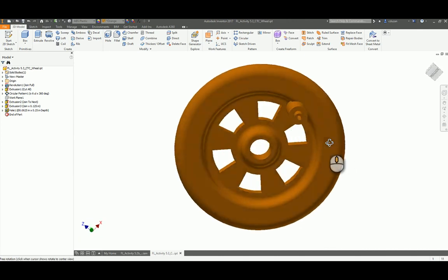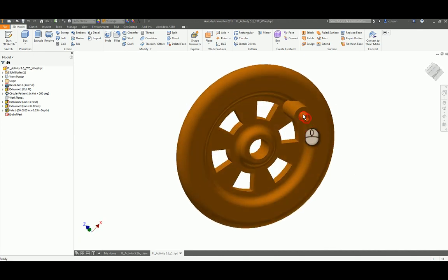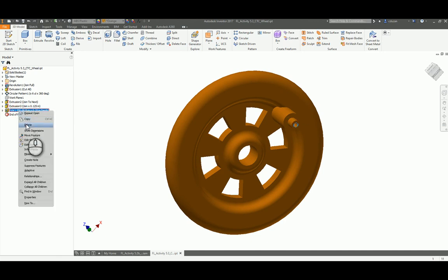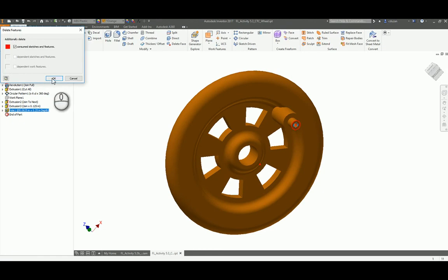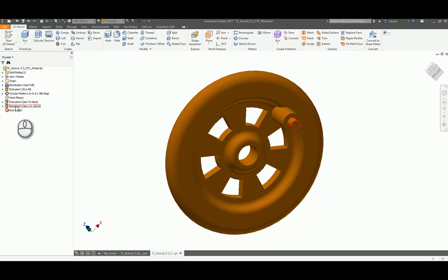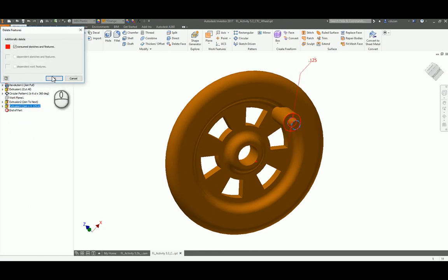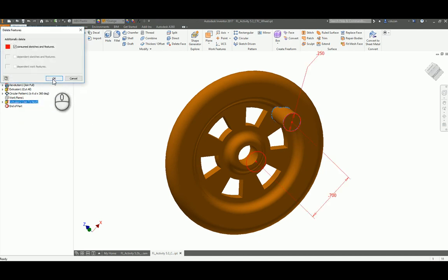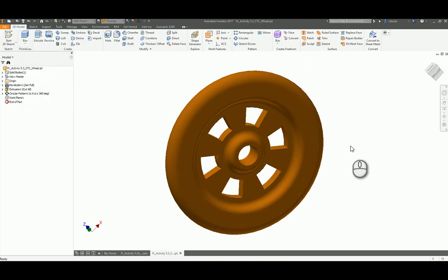Okay, so now when we take a look at the wheel, we see the cylinder and this peg sort of thing on top with this hole. We can get rid of all this. We just want those wheels to be smooth because there's no purpose for the actual linkage arm or the linkage peg. So I'm going to come here to my first hole at the very bottom and delete that with the sketch that we used to create it. Also come here to this extrusion, and we'll delete that with the sketch that we used to create that. And this extrusion here, we'll delete that with the sketch we used to create that. Now we can see that this is a smooth wheel. This is the wheel for a custom train car.